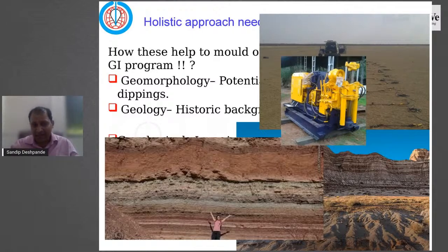The geophysical investigations significantly add value because they give continuous real-time line information rather than point information. Once you have multiple line information, you can develop 3-dimensional profiles, and the uncertainty in these profiles points to the surprises where you can investigate and assess, and then accordingly plan your geotechnical studies further.